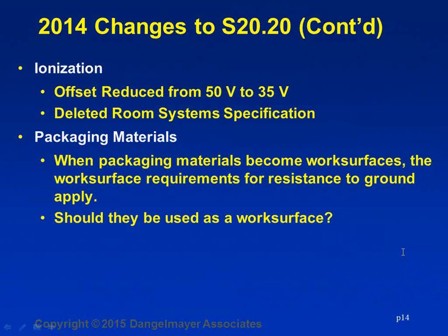No, I was just going to say that's actually what we agree with. So yeah, that's a good one. Just to offer up a conversation point, though, the first thought that comes to my mind when you say packaging materials is an ESD bag, and certainly that's where one of the issues has come up. You see this in witness audits as well as in our audits, where someone has taken a board, for instance, out of an ESD bag, placed the ESD bag on the table, and then put the board on top of it, thinking that's a safe situation.